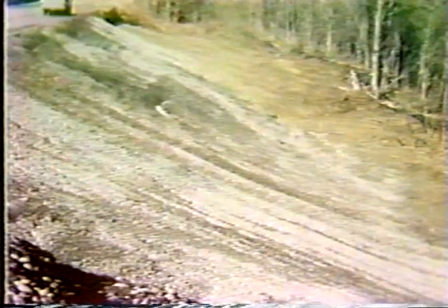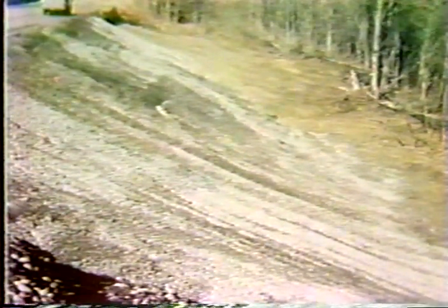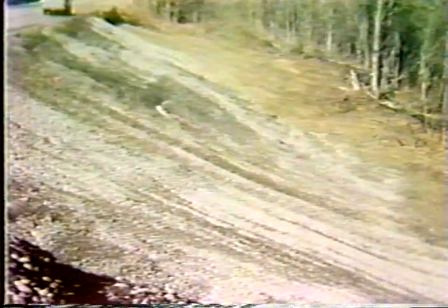Fortunately, they got to the problem soon enough, and here you can see some more sloughing off of the back wall. They did get back and backfill the material. Eventually, the geotechnical engineers speeded things up, and they got the thing repaired. But what I want to emphasize is that when you do a shear trench, construct it in segments and backfill immediately. If you have to work 24 hours a day to keep the stone there, keep it there and backfill.